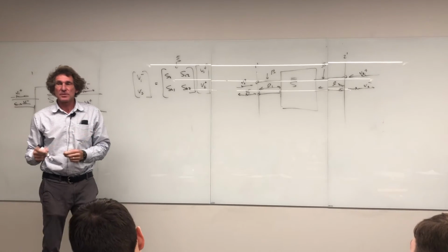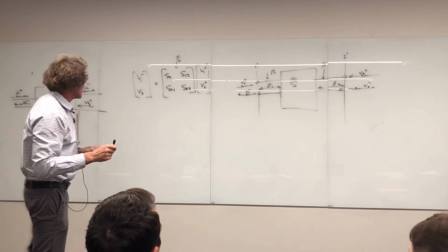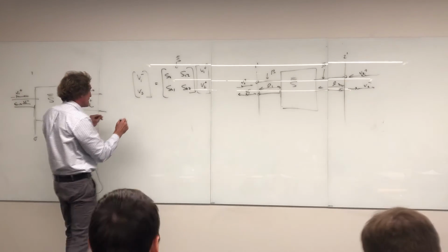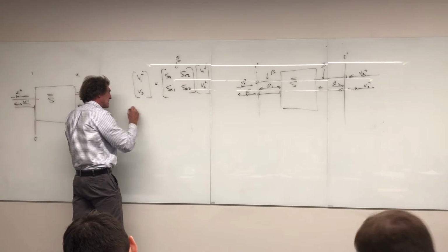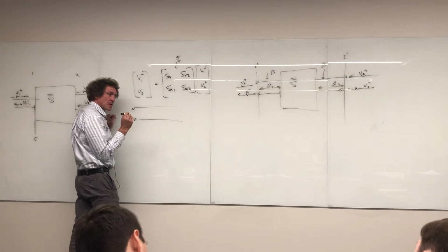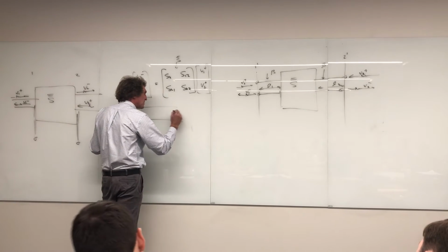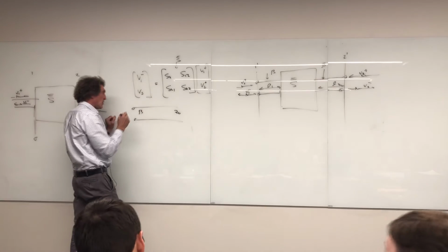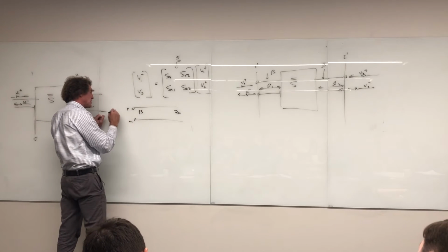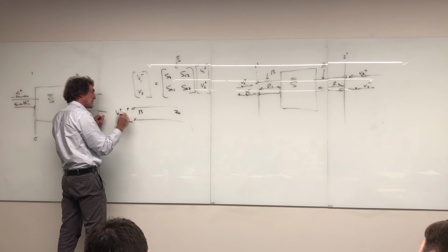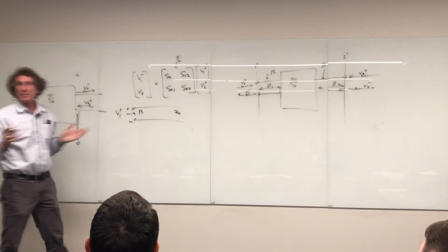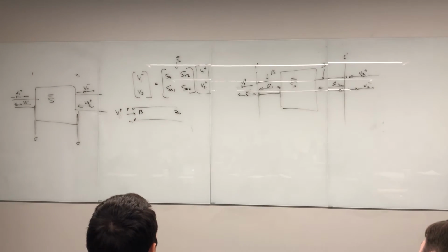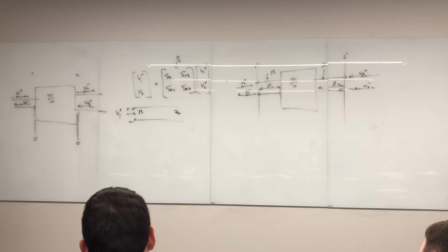A lot of times electrical engineers where you're at don't see this. If you just have a transmission line, let's assume it goes on forever, and there's some characteristic impedance and some constant beta. Well, if I have a signal right here, I'm just going to call it V1 plus, coming in. It could be 10 at an angle of 0 degrees. It could be anything. Remember, we're in the phasor domain, so it's magnitude and phase.